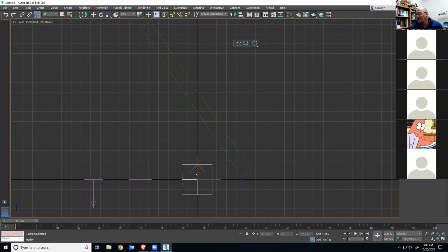So question. Yeah, go ahead. With the spray and the deflector, do you link the deflector to the spray, or the spray to the deflector, or does it matter which way it goes? Spray to the deflector. Okay. So you're binding the spray to that force or the deflector, right? Now I have two things: a gravity force and a deflector, and I clicked from the super spray to each of those individually. Okay, so the spray to whatever. Yep.